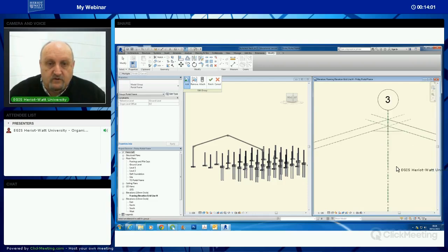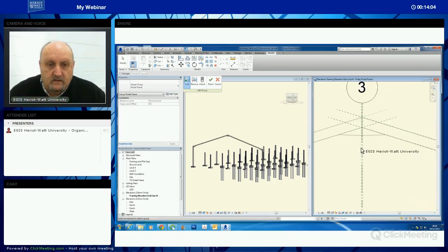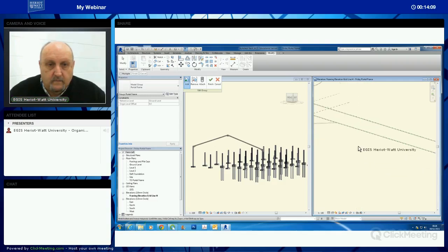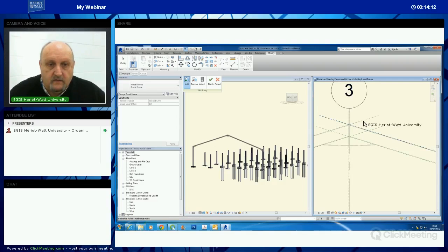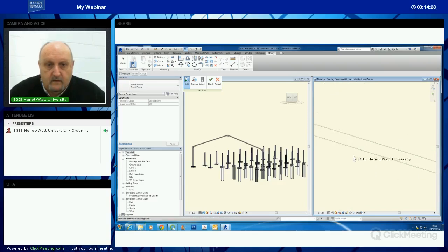And then the two now which are in the middle, either side of the grid line, so that one there, that one there. Any more missing? That one up there, that one there. I've got all these. If you don't have them, they should turn blue. That's fine, I've got everything there. The central weld plate, that needs to go in. And over here, I'm just left with the reference planes and the haunch. I think I've got the haunch, so it's the reference plane there. This one here I've got that one. It must have been extended from the other side.